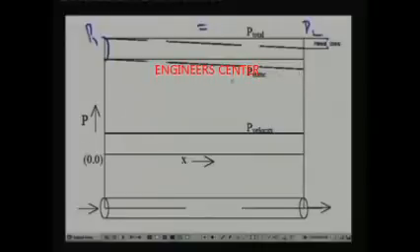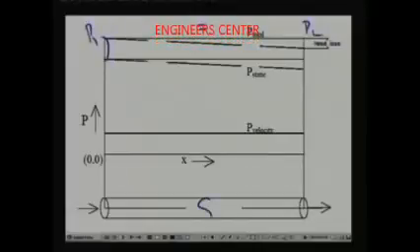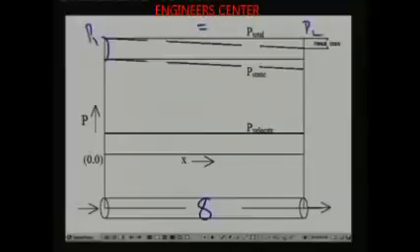Whenever you have viscous flows, and if you want to have the same pressures at the inlet and outlet, or if the inlet pressures are greater than the outlet pressures, then what we have to do is use some kind of a pump or a fan. For example, if I am using a pump here or a fan here, okay, then it is possible to maintain the same static pressures and the total pressure at the inlet and outlet.